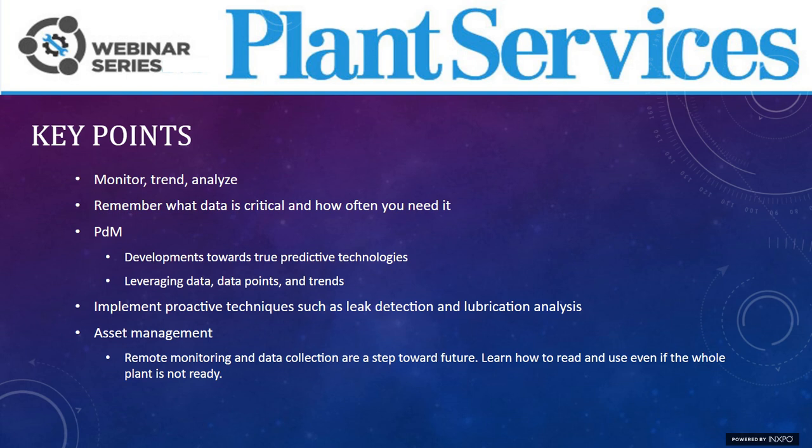To summarize here, there's a multitude of data points that you can collect to better monitor and manage your compressed air system to help improve reliability, increase your uptime, and reduce maintenance costs, as well as increase the energy efficiency of your system. Understanding what points are critical to your operation and which are highly useful but not critical is a big step in effectively monitoring, tracking, and analyzing your compressed air system data. This will also help you avoid data overload. Remember that non-critical data is still important, but you might not review it as often as critical data.